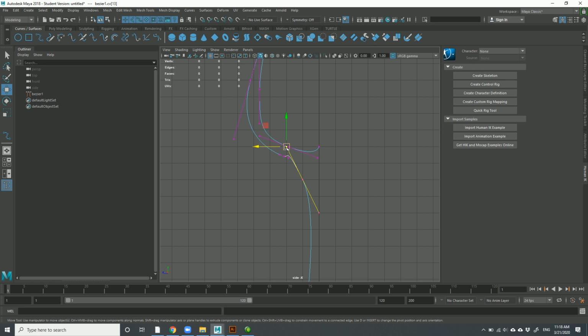So I've selected that, and I just want to do that. Actually, I don't really mind that, but I want to show you something here. So if I take this, let's say I just wanted to modify just this thing here. So what I can do here is hold down Shift, right-click, and go to Bezier Corner. And what that gives me here is this.